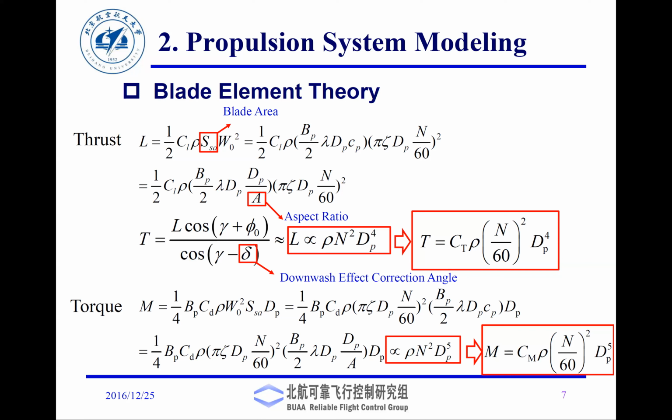And that lambda factor is because I don't have a full circular blade. I just have a part of the blade that is kind of rotating. So that is the assumption for the area, multiplied by the speed, where again Dp n by 60 gamma pi gives me the angular velocity, and that is squared. Once you expand that equation, you do a little bit of mathematical jugglery and call something called aspect ratio.